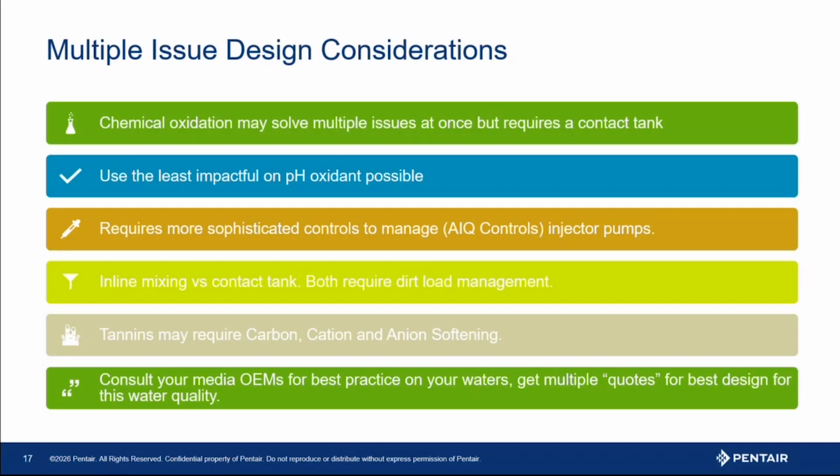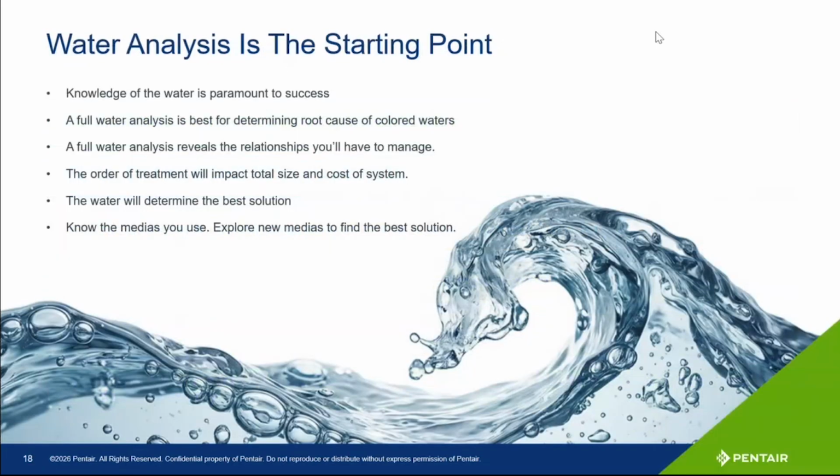AIQ controls, we do have relays available to control injector pumps. So we do have synergized equipment to do so. Inline mixing versus a contact tank, depending upon your situation, both require dirt load management. Tannins may require activated carbon, cation, and anion softening. So it may be a three-step process. Always consult your media OEMs for best practice on your waters. Get multiple quotes for the best design for this water quality based on the technologies you select.